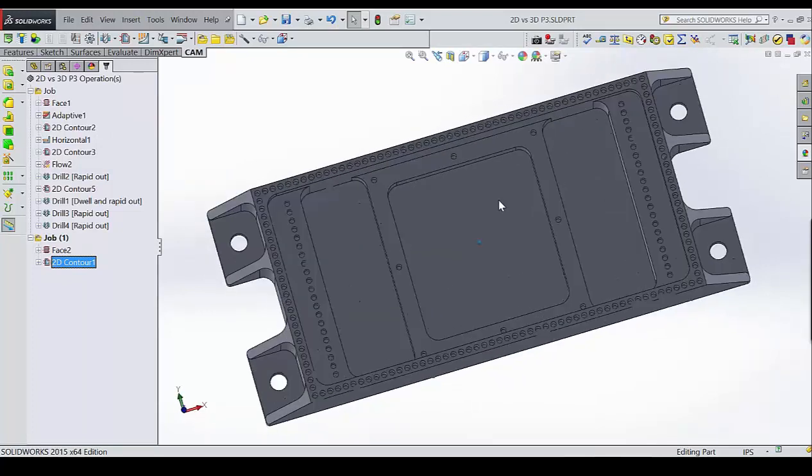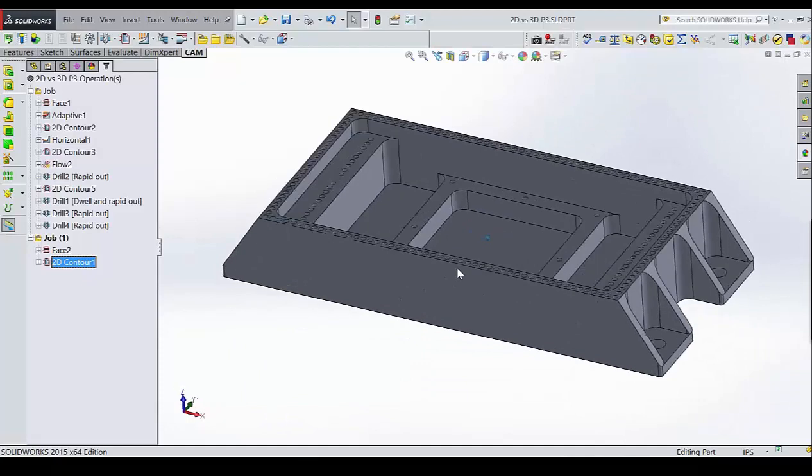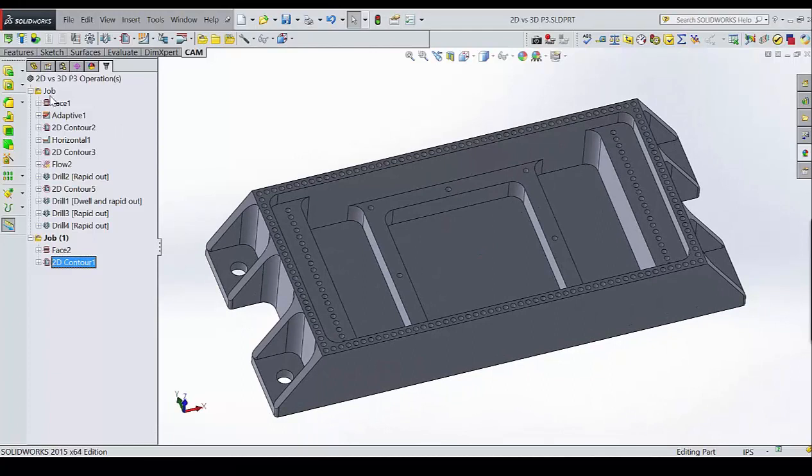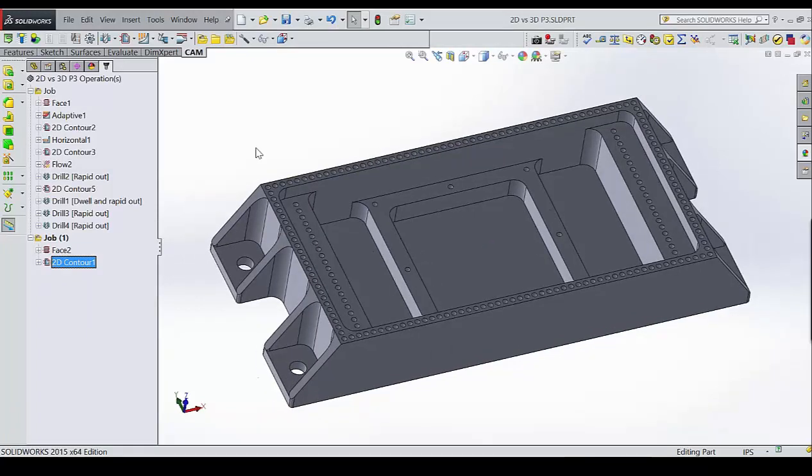It's basically like an electronic housing or a little aerospace, different kind of housing. Part of my background, so it hits my heart a little bit. So you have some cavities with different levels. You have, I think it's well over 150, odd 80 tap holes. They're all at 3 different Z levels, but they're also 3 different thread depths. So it could be a lot of selections if you don't have a nice template set up. So I'll show you how to set up a template to spot drill and tap. I think it's 7 mouse clicks it takes to do all of those holes. So let's jump right into it.